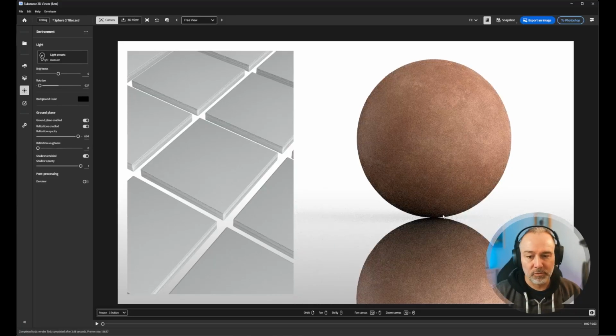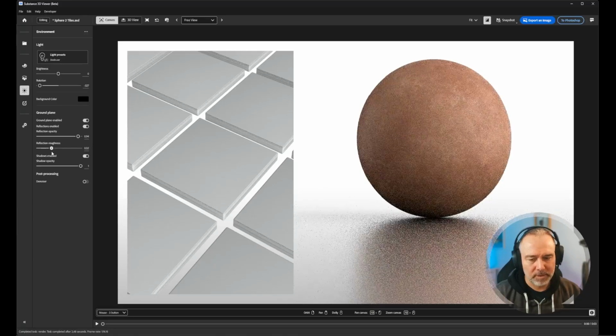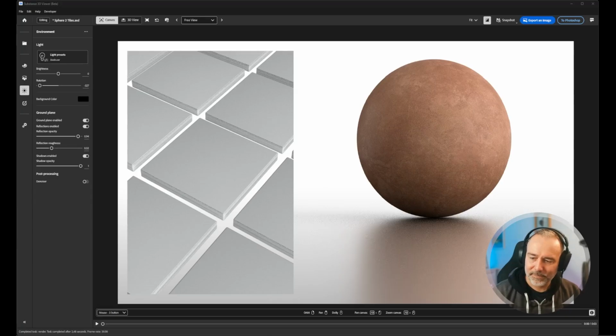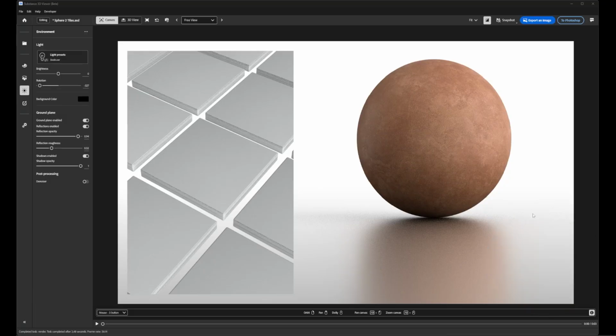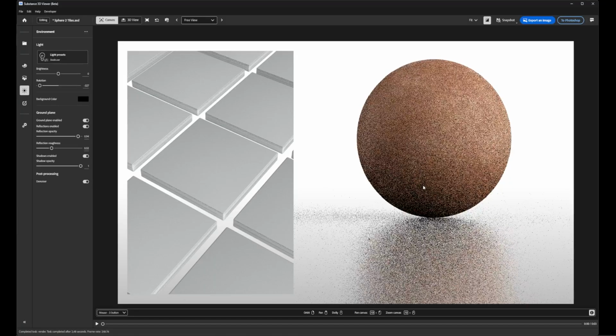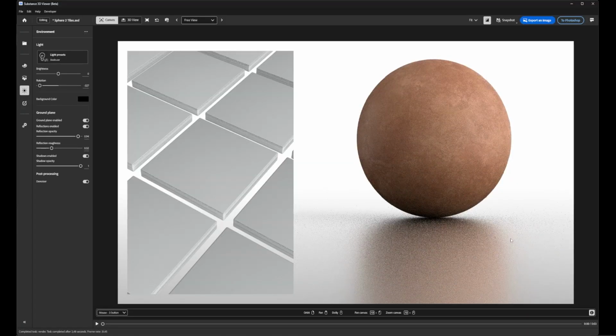I can also change the roughness. If I put it to 0, well, you have a pure mirror, but that's not what I want. But you can do something like this, which can be subtle. I'm going to hide my face because you see the lagging. Here, for example, I like it a lot because you have some of the color which are there. It gives a good result, and after a while you can also activate here the denoiser. When I do this, it will make the same work of simulating the light rays, and at the end it makes another pass to remove all the small noises that you could have in the image.